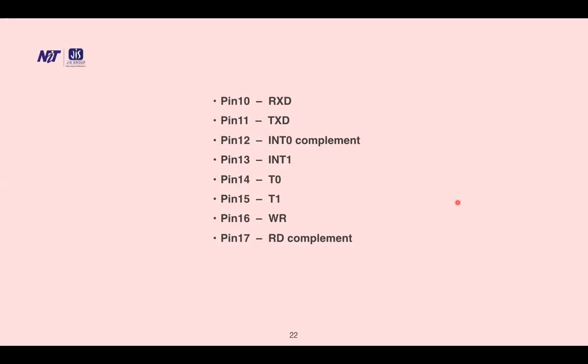Pin 10, it is receiver data. Pin 11, transmitter data. Pin 12, INT0 complement. Pin 13, INT1. Pin 14, T0. Pin 15, T1. Pin 16, write. Pin 17, read complement. This means when it is 0, it will be read, and when it is 1, it is not activated.